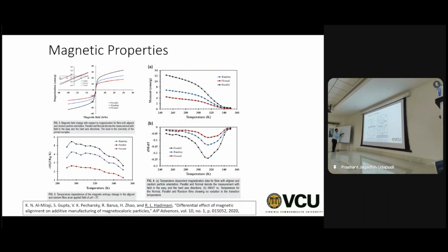A lot of the times, if you measure Young's modulus, electrical conductivity, thermal conductivity, or the magnetization, the long axis tends to be the easy axis, meaning you find higher property, higher conductivity, higher magnetization or magnetic permeability, whereas the smallest axis will have lower.